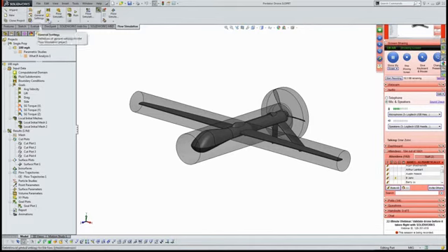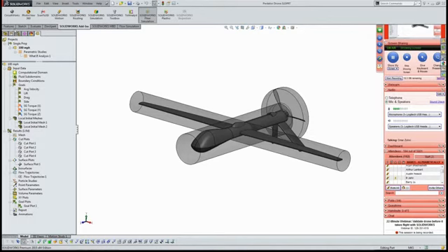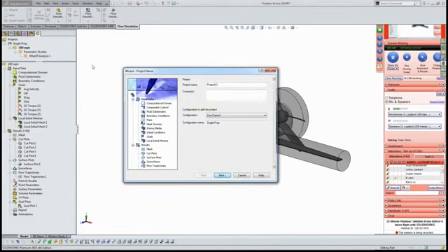Flow simulation is turned on via the SolidWorks add-ins, the same place where plastics, motion, or the FEA solver is turned on. One of the nice things available inside of flow simulation is what's called a wizard. This wizard walks you through all the prerequisite steps required to set up and run a simulation. I am not a huge fan of installation wizards. Probably no one on here is, because all you do is sit there and press next, next, next. No one's reading anything. That is not how the flow simulation wizard is. So I'm going to call this flow run, live run.